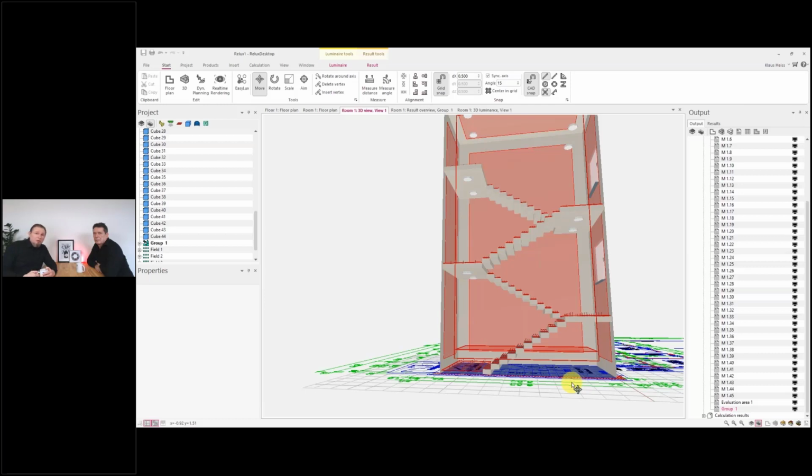It's also possible to use BIM models. If you have a Revit model, then Revit into Relux is a common way. IFC to Revit to Relux is also a common way. We also have enriched capabilities of 3D import. If you have a 3ds, OBJ, FBX or Collada model, whatever in 3D, you can import it into Relux. At least you have the geometry, not the measuring areas. Measuring areas you have to do yourself, but at least the 3D modeling is done, by a model out of any other software where somebody else has modeled the staircase.